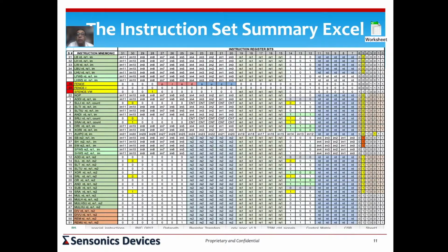So I was talking about the last 2 bits. If you look at the first 2 bits, bits 0 and 1, they are all ones in these instructions. And you would also notice that the first 6 bits, 0 to 5, are never all ones. When they become all ones, then depending on whether the 6th bit is a 0 or a 1, it's either a 48-bit or a 64-bit instruction word. Since these are all 32-bit instructions that we're talking about, those will not be all ones. So that's how the instruction fields are defined. And when bit 0 and bit 1 are not all ones, it's a 16-bit instruction.